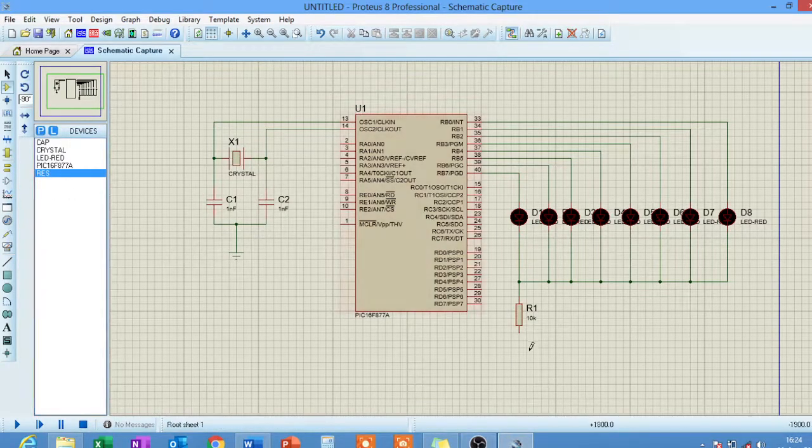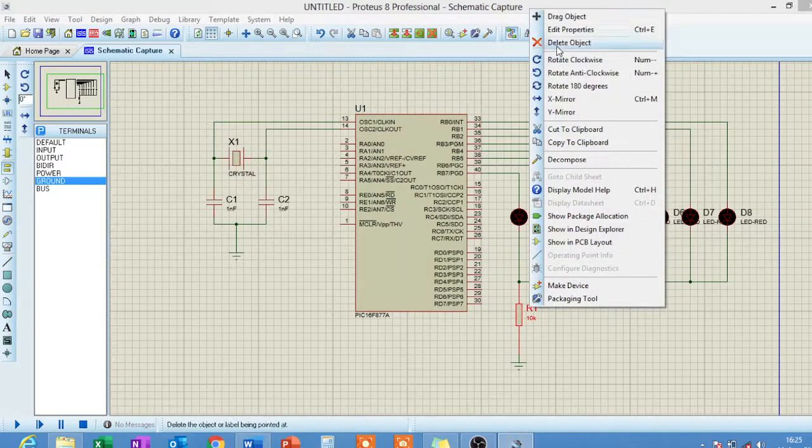So I can decide to connect this one to this ground here, but I would prefer to have another ground terminal there. It's the same. In a circuit like this, whether you have 100 grounds, they are treated as a single connection, so it doesn't matter. Alright, so I can have that. Then I can start setting up these things. That is now to say what should be the value of my resistor.